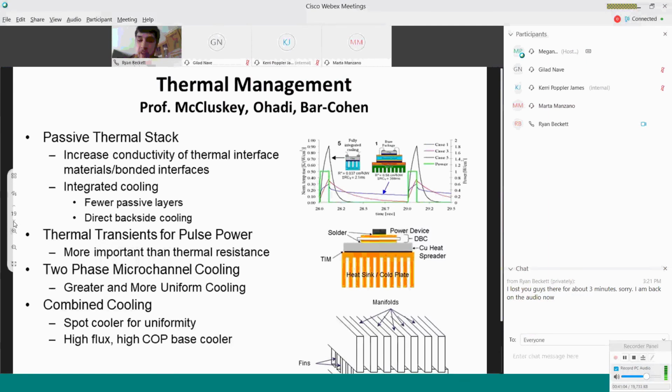The next thing is, what are you going to remove the heat to? Well, typically you either have to flow air by something or you have to flow liquid by something so that the airflow or the liquid flow can pick that heat up and transport it out of there. So we look a lot at how do we do convective heat transfer through air and liquid-cooled heat sinks.